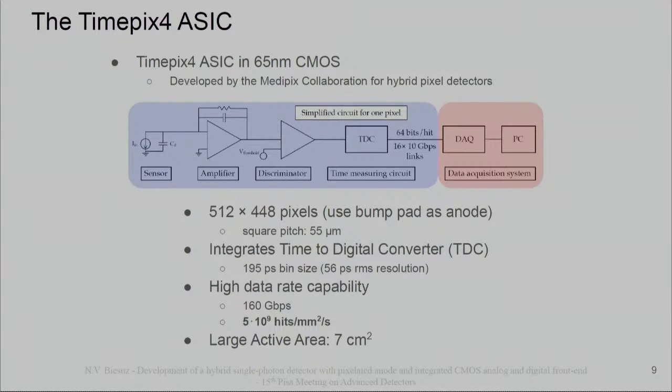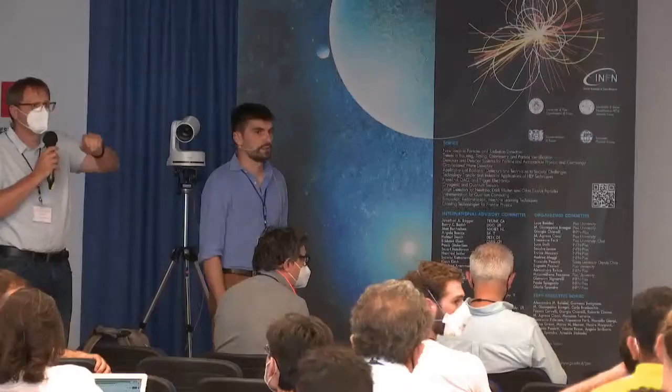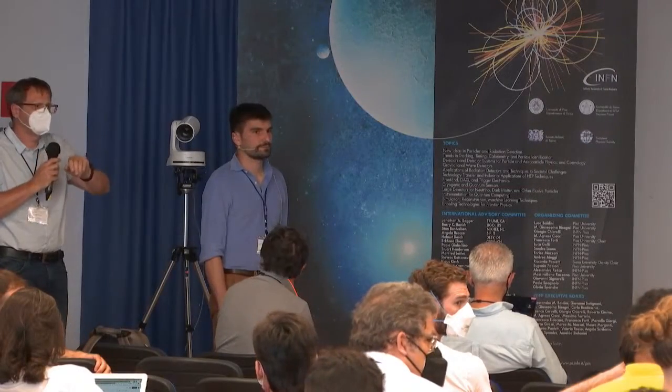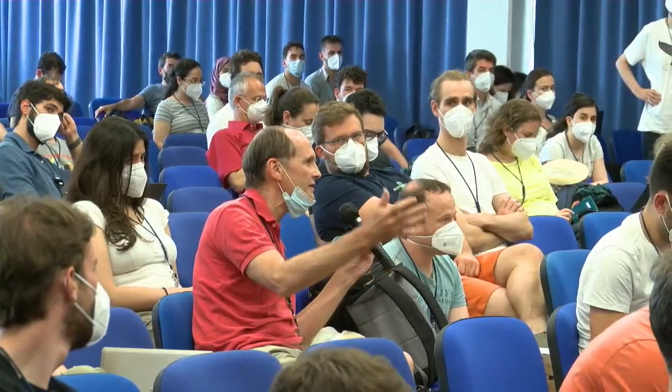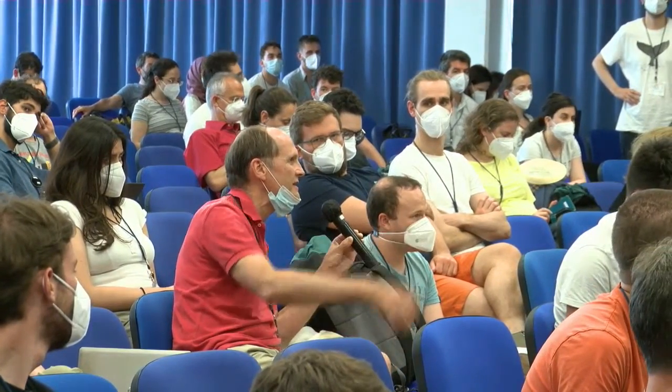So basically here you have the bare Timepix ASIC. You have a pad which is, I don't remember the number, I think something like 20 micrometers of radius, a round pad. So really here the rise time is given by the creation of your signal and by the MCP. The preamp contributes, I mean, at some point the speed of the Timepix is, I don't know, 80 megahertz, something like that.